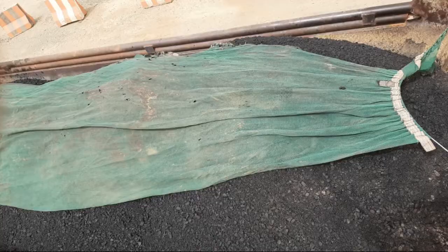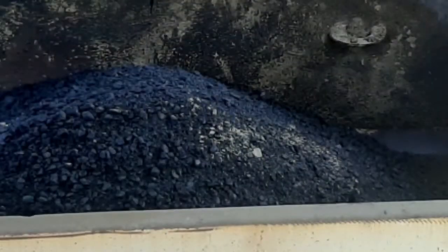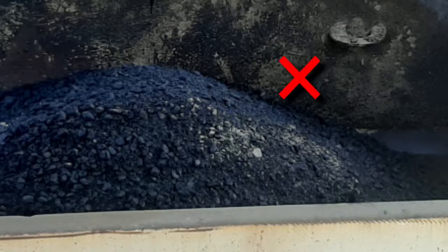Mix 2 tons of asphalt and discharge in the truck. Then check visually. If asphalt is good, then continue your production. If asphalt is not good, like uncoated or looking fine or looking coarse, then you can make new adjustments. You can increase or decrease the percentage of aggregates. You can increase or decrease the weight of bitumen.